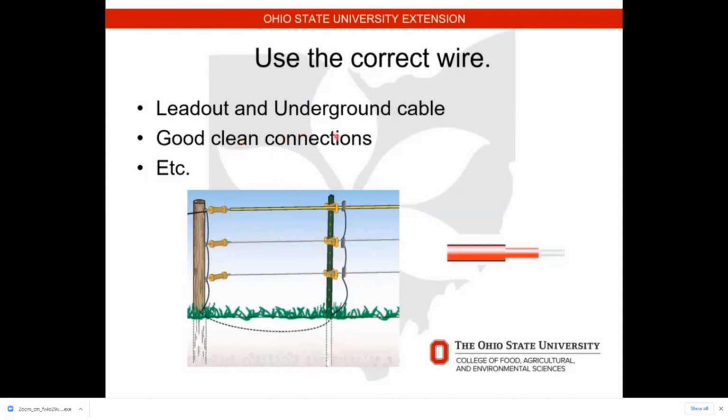But you want good, clean connections. And if you are going to install some of this underground wire, especially under driveways, I'd put it through a piece of junk plastic pipe that you got, just to help protect it even more.